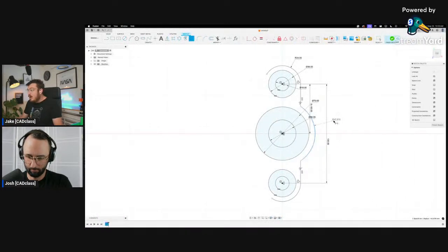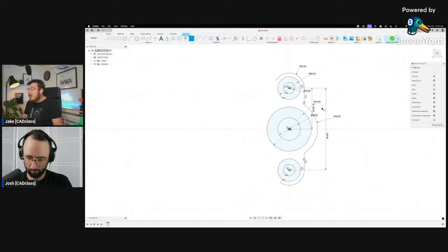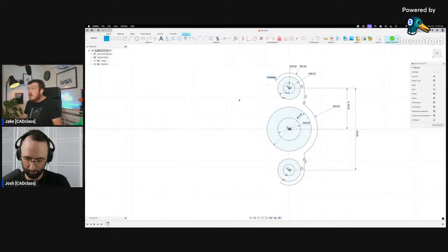Radius 45. Oh my gosh, this is getting messy already. This is why we say to click and drag the dimensions away from your sketch, because it makes it so much easier to see what the hell is going on. Okay. And then, again, 2 tangent lines coming off on either end. I probably should have made that with a line tool, so they were already perfectly tangent.